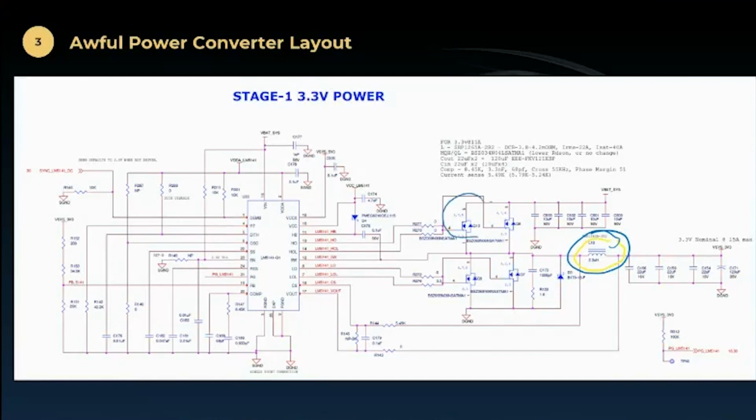In this case, these switches are outside. We have two of them in parallel, two high side switches and two low side switches. So this is a relatively big buck converter. But still, from a layout standpoint, it's the same thing. We're identifying this switching node, that node of the circuit where the dV/dt is very high. We need to keep that node small in the layout, and we need to locate it so that it can't couple to other circuits, particularly the input or the output of the inverter, because the input will take it back to the LISN for a conducted problem, and the output will take it to the rest of the board, which often can result in a radiated emissions problem.